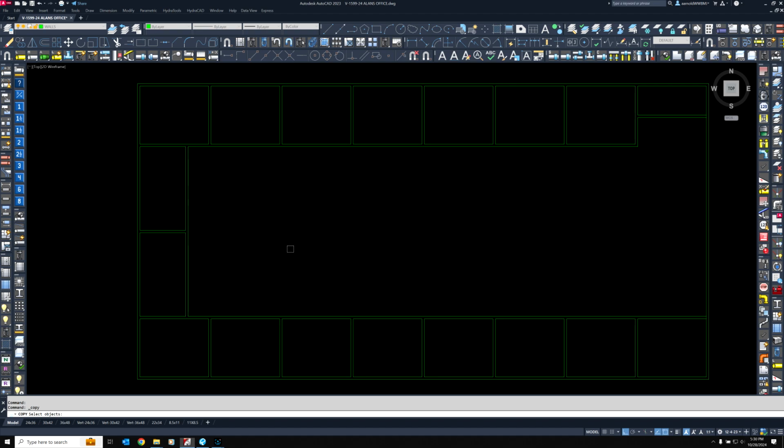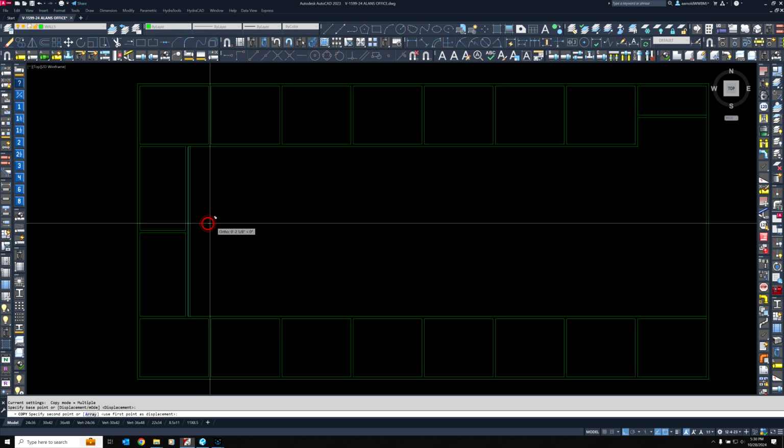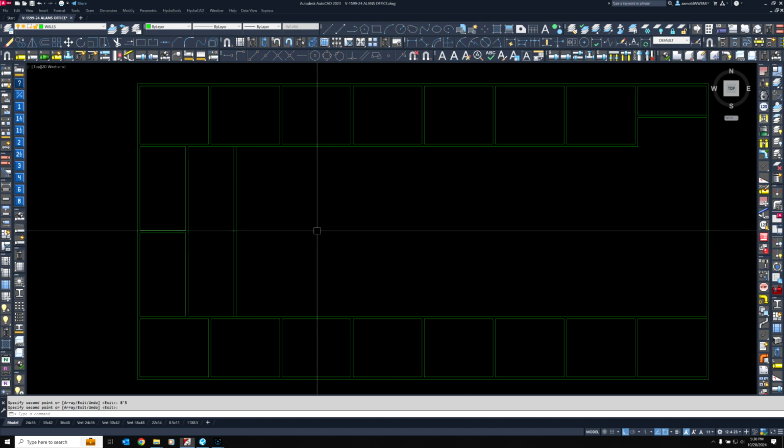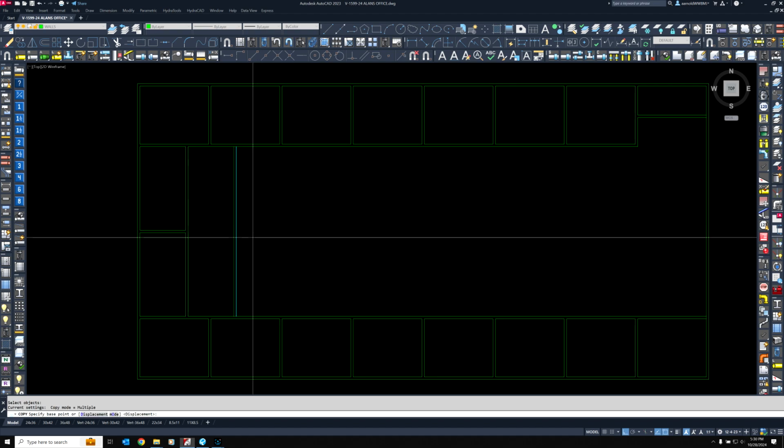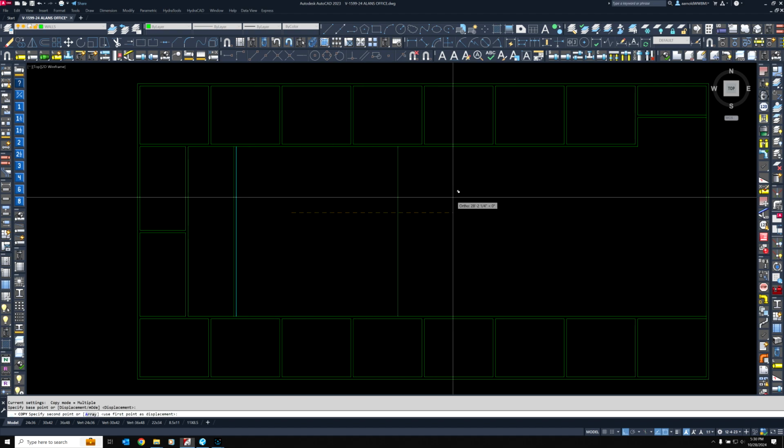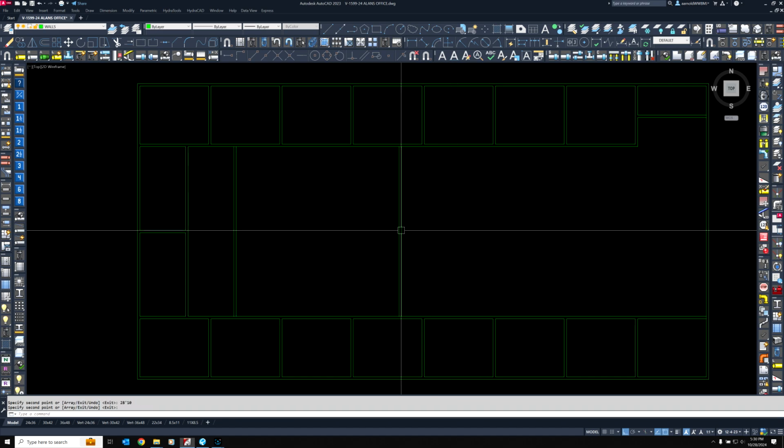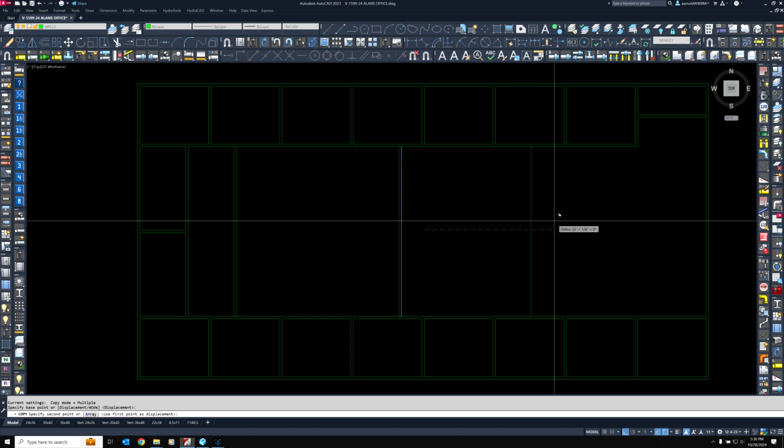8 foot. There's an 8 foot hallway on this end between the restrooms and the conference room. 8 feet. Copy it, then 8 foot 5. Then the conference rooms are 28 foot 5 long. So let's repeat copy, left click, enter, left click, and tell it to go 28 foot 5. Then there's a 5 foot wall again. So how about 28 foot 10? And then we have 28 foot 5 to the last wall. 28 foot 10.